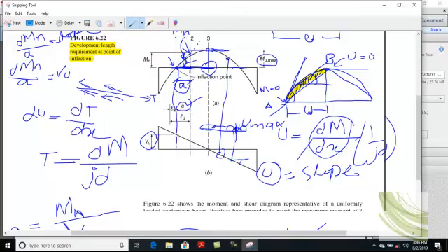But if this a is greater than or equal to Ld, and this Ld is somewhat far away from the point of inflection, as the moment at this point becomes 0, you don't need this distance behind that point. But if you extend the bar behind the point of inflection, you make yourself more safe.